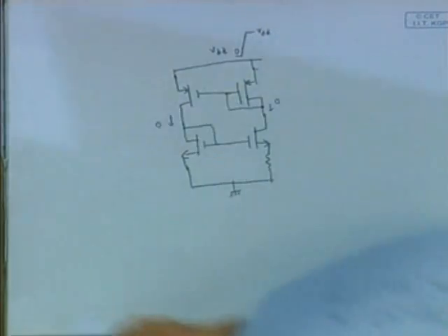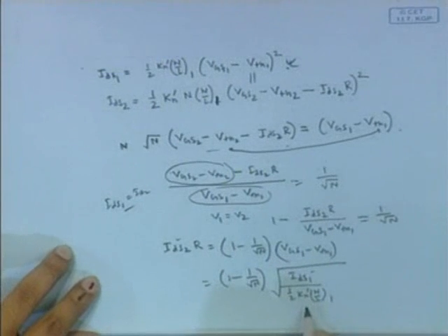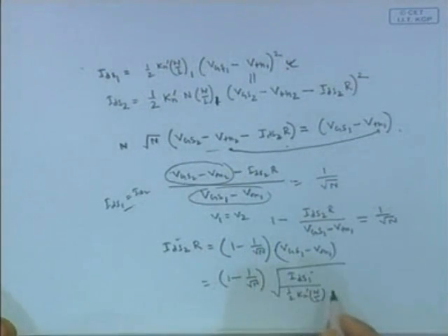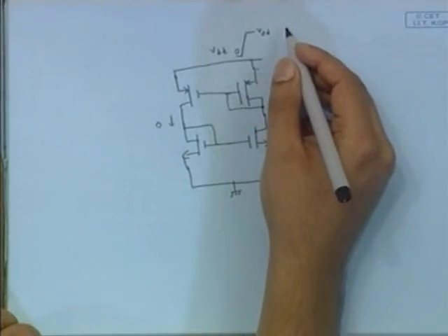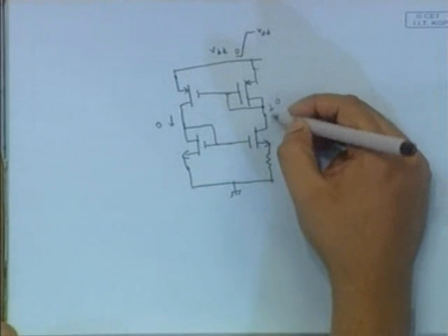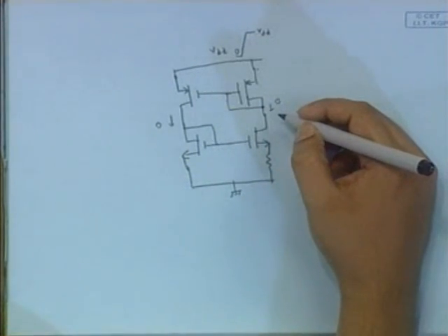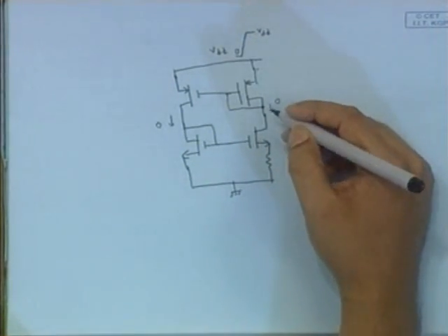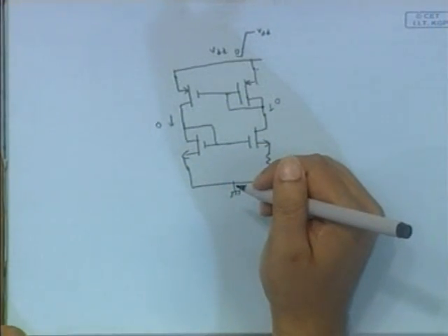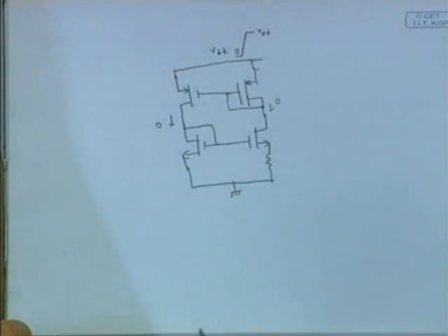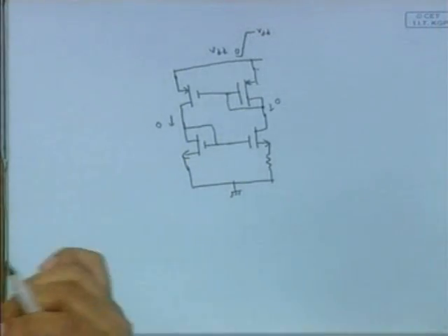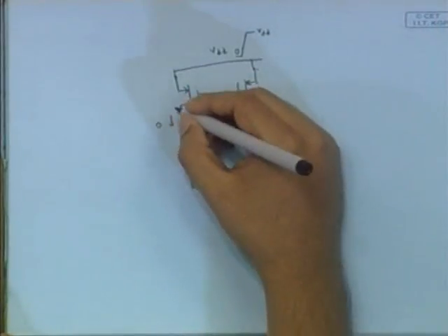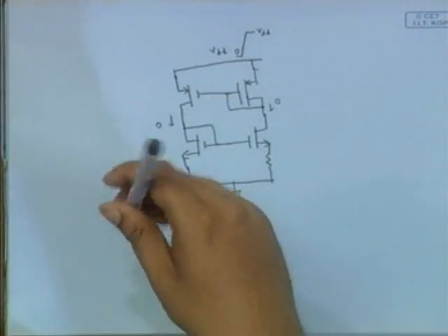So in this expression there is no VDD term, right. So only a change in VDD will not cause current to flow through these circuits, right. So at the initial stage when you just power on this supply, in some artificial way you need to introduce some amount of current through the circuit, okay.